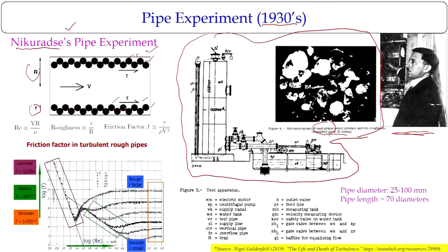So you can see that because of this roughness, your flow characteristics can change. Also, we know very well the Reynolds number also controls the flow behavior. So we want to know what the wall stress, the tau value, would be, what the velocity distributions would be, and what the energy losses would be when you have a pipe length of L, with information about the roughness and the flow Reynolds number.